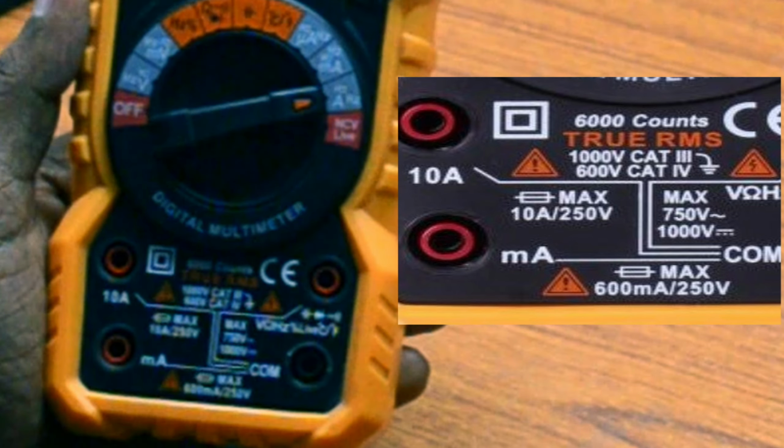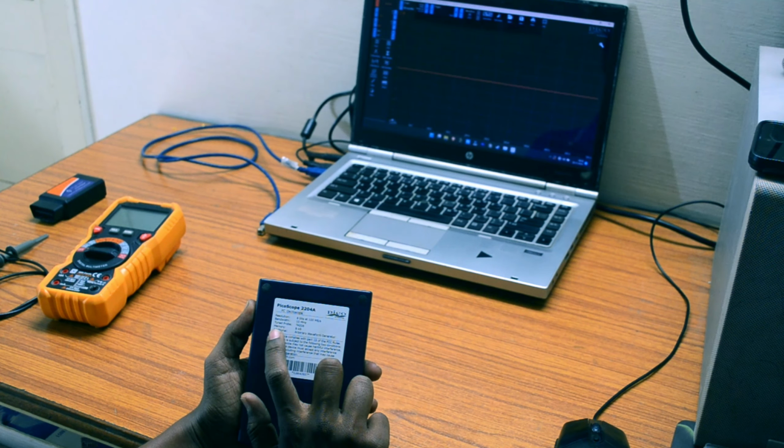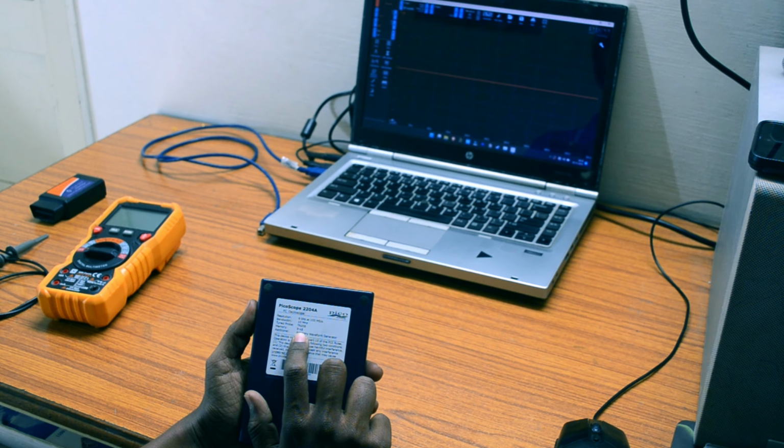Now I will take oscilloscope. That is, I have PC based oscilloscope, that is PicoScope Series 2000, the model is 2204A. This is a 2-channel oscilloscope, and if we see the specifications, the resolution is 8 bits at 100 megasamples per second, and the bandwidth is 10 megahertz, and it has a storage capacity of 8 kilosamples.